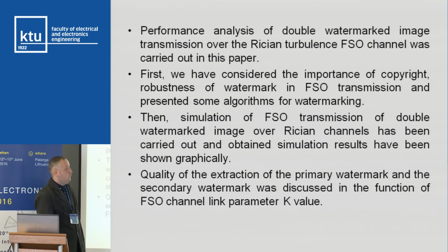Free space optic channel is modeled by Rician model. This Rician model is a very general model that can be used not only for free space optic propagation modeling. And we have provided this performance analysis in the function of system parameters, and the system parameter that is observed mainly is parameter k of this Rician model.